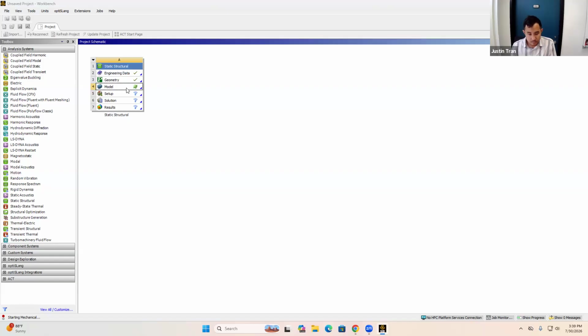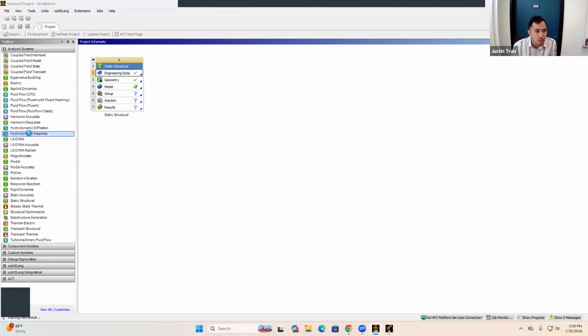If we were working on a bridge and we wanted to do the fatigue life on it, is there a way to add that in? Yes, it's one of the custom material properties that you can add in. Once it loads, I'll show you. On the left, you click on a material, there's a menu there for fatigue properties, and you click and drag SN curve. You just have to input it manually. Sometimes that data is published in a material data sheet, so you can input it from there. Sometimes you might find it in the literature as well, where people have done material testing.